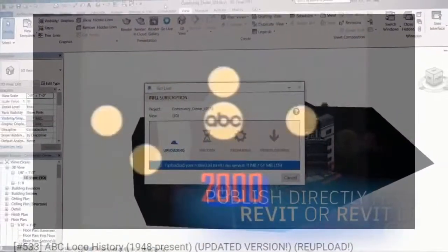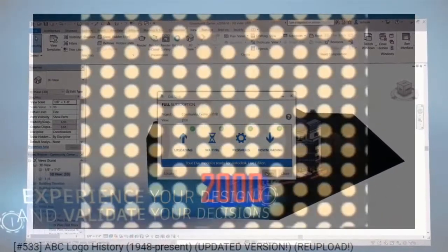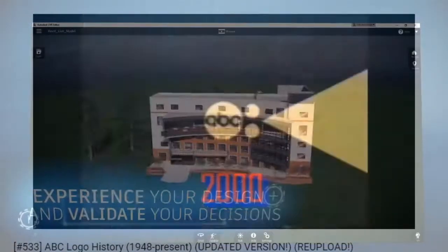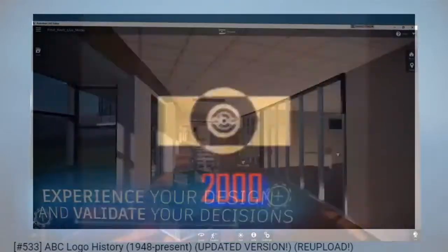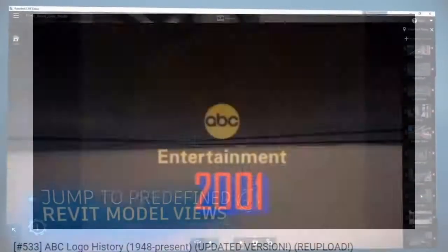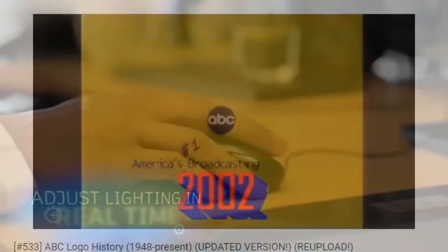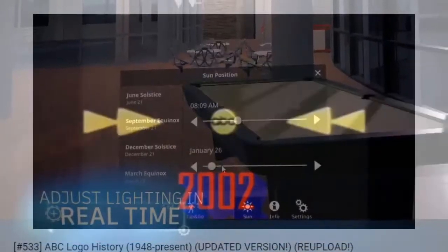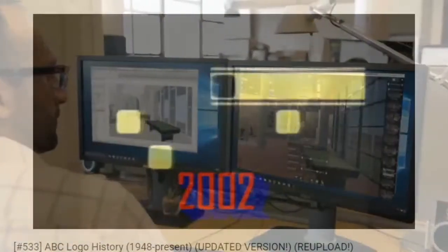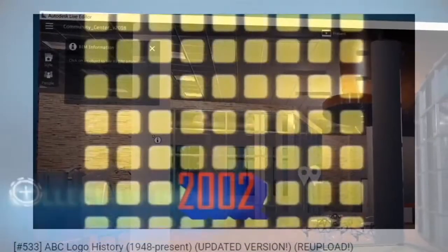All right, so we have our south elevation open, we have our ground floor elevation open, ZA, zoom extents. And we have this 3D view of the floors. Okay, so click the architectural tab and select floor edge from the build panel. It's also available in the structural tab. Slab, floor edge. Let's do it from the structural tab. Actually, you know what? Let's follow the directions, Mike. You know me, I'm always trying to reinvent the wheel sometimes. Slab edge.